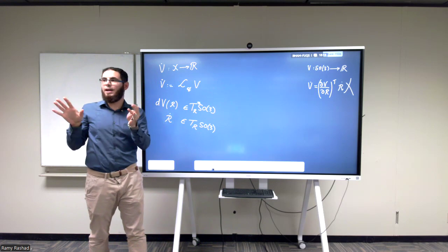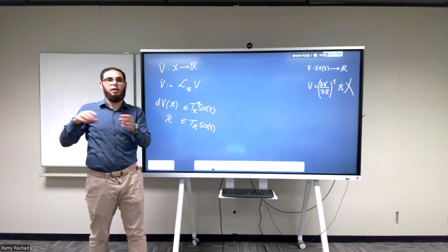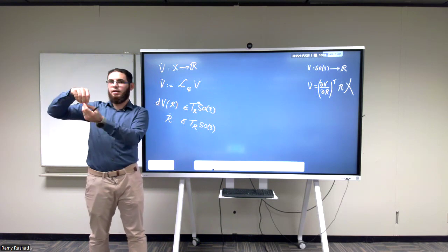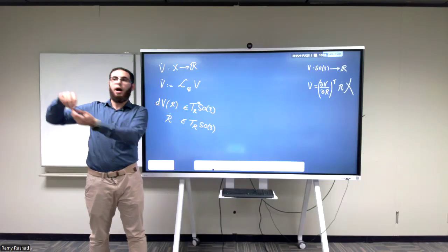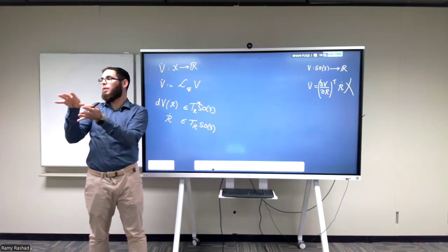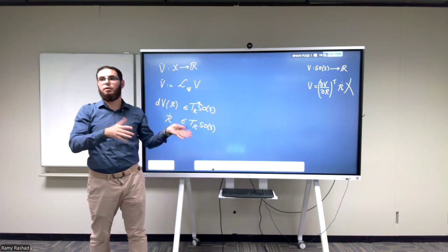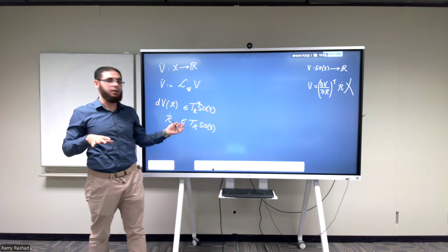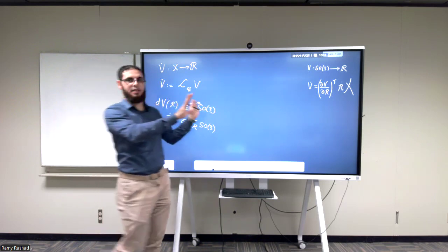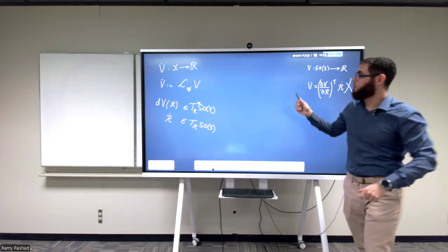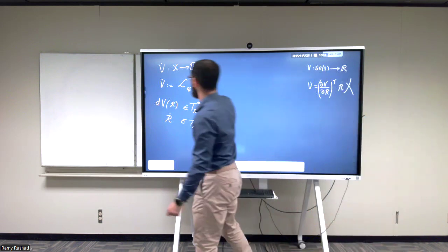Okay, the only way that you were able to do it so far is by taking Euler angles, by taking your actual Euler angles minus the desired Euler angles, multiply them by some proportional and derivative gains, and you get the result. Okay? But again, this is all working in charts. This will be the geometric way of doing it. All of this is for next time. Okay, I just want to show you why this is important.